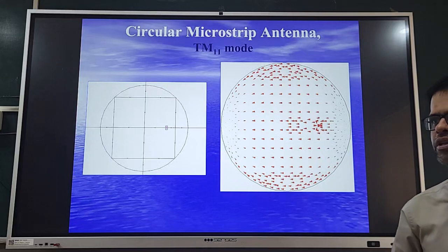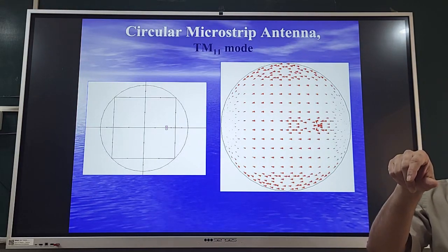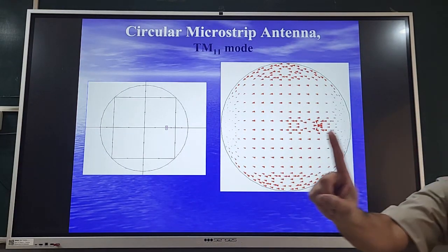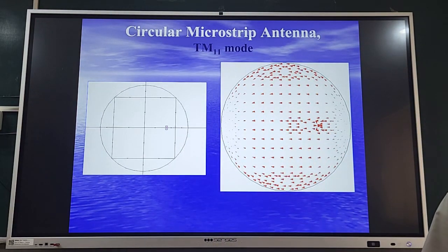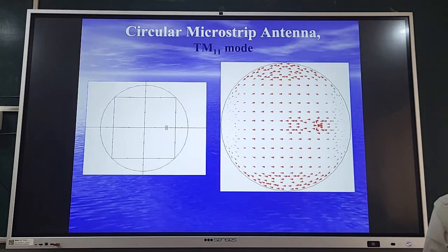So at the output of the source, apart from the fundamental frequency where you have tuned your source to give output, the higher order modes are also present: 1 GHz, 2 GHz, 3 GHz and so on. If you design at 900 MHz, then 900, 1800, 2700, all those will be available.